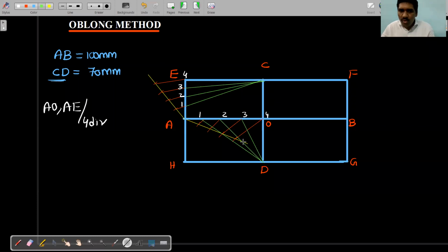Okay. Now you have to do one thing. You just extend this line. Okay. This D1 line is there. Now extend this D1 line up to this point. It's my extremity. Okay. We'll see that one afterwards. In the same way, just mark the point. Extend. In the same way, these also we have to extend. You can see, all of you can definitely get some intersection points like this. Okay. So I'm starting the ellipse from here, please check it.